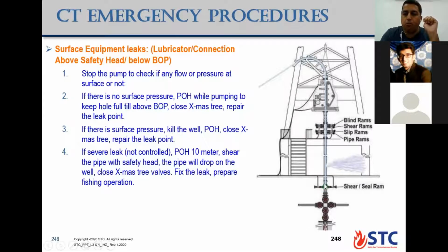You can pull out fast and close the Christmas tree after you kill the well. Or you are deep inside the wellbore and cannot manage this situation, and you have a severe leak like a high H2S percentage, gas well, or high pressure. At that moment, you will take a decision. But the safer and quicker option is to pump kill fluid inside the string of the coiled tubing to kill the well, and after that, you pull out.